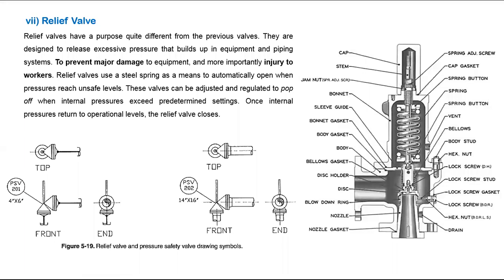From the water tank, if you store the water in the water tank and take the water supply from the water tank, the ground floor water pressure will be 6 bar. Because your building height is approximately 60 meters, 6 bar pressure will be there.